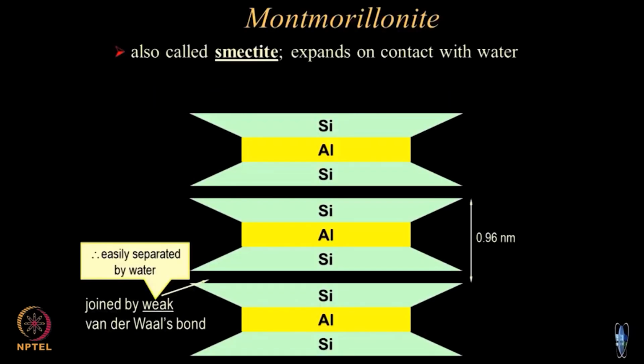Is this okay? Then comes the montmorillonite. People have special interest in this, because this is a mineral which is hyperactive. It has a lot of values in present day science and technology, but it used to be treated as a curse some time back. So, you go to the central parts of India, Maharashtra, Madhya Pradesh, Karnataka, where you have black cotton soil. The constituent of the black cotton soil is montmorillonite. It has very strong affinity towards environmental changes. During rains, it will accumulate water in it, becomes fat, and when rains go, it shrinks.